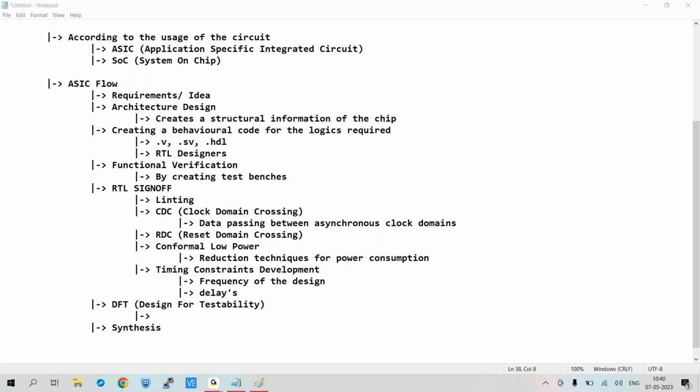Yes. Right. So those required parameters, or modification in the netlist if required, will be done in this particular DFT. So ATPG, JTAG, stuck at 0, stuck at 1, and also these DFT persons will be able to give an idea about the failures.